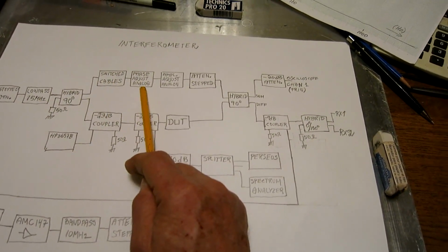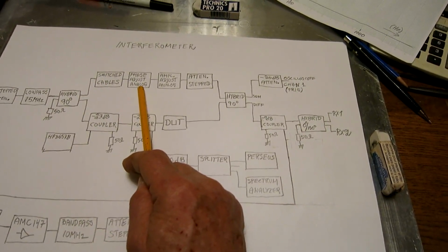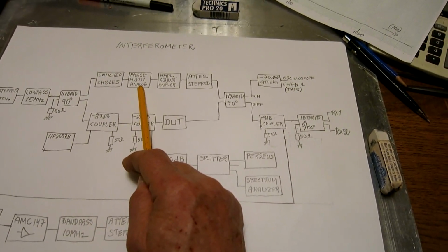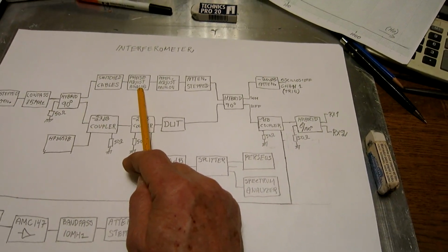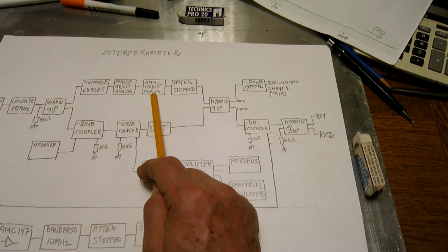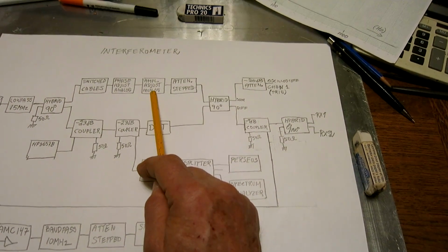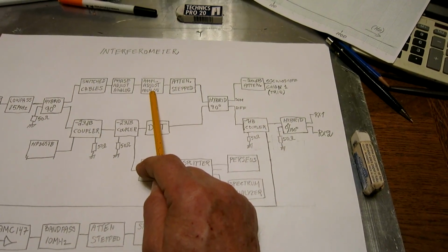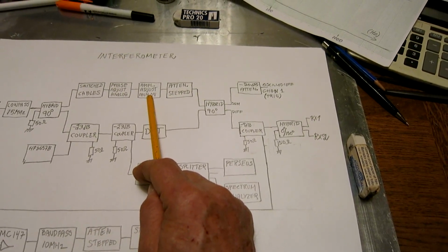Then there is an analog phase adjust. It's a hybrid and a dual gang capacitor, and the second, much smaller dual gang capacitor for fine adjust. Then there is an analog amplitude adjust. It has several, 3 of them, variable capacitors with resistors in series.